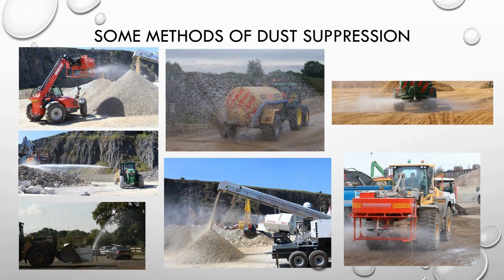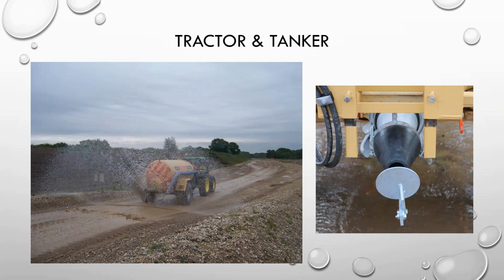We have found the most common method used for dust suppression across the board is the tractor and vacuum tanker approach. Tankers used in dust suppression can range anywhere between 5,200 litres to over 9,000 litres. The safest type of tanker to use would be ones fitted with a hydraulic vacuum pump as opposed to PTO-powered pumps. Pressure-fed units are normally fitted with a rear splash plate, making it particularly suitable for damping down residual dust on haul roads where a high-volume water application is required.